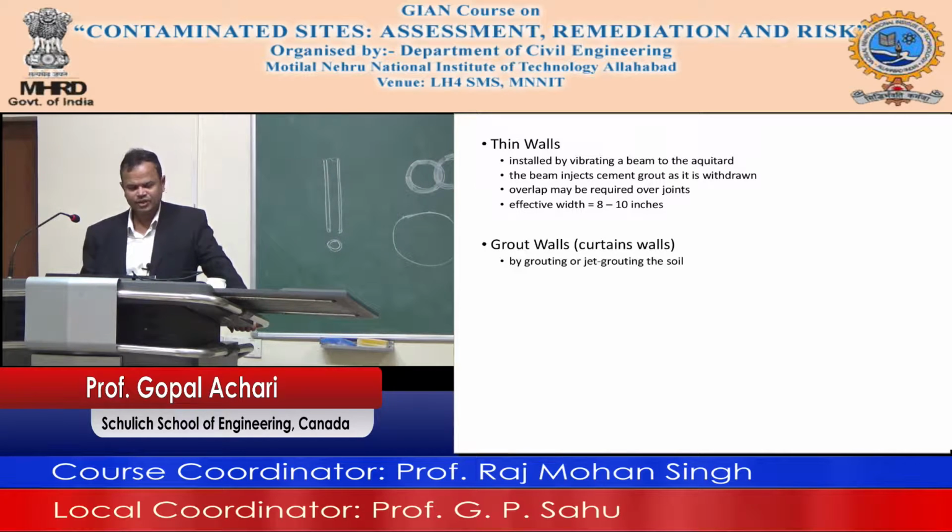For that you need this leachate collection system and geotextile, and the geotextile prevents sand and other things from clogging this area. So that's why you have this geotextile at the top and the bottom, to prevent clogging of this gravel here. The gravel supports this leachate collection pipe, and that's the base. That's how the base of a landfill is prepared.